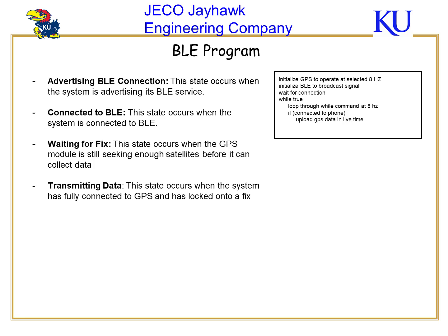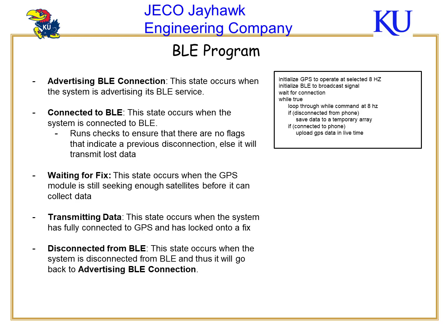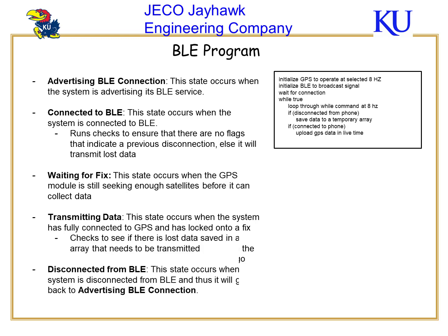This was a great proof of concept, but the only problem was that there was no way of reconnecting to the device or logging data when the device is disconnected from the phone. The second iteration of our program would ensure that upon disconnect, data from the GPS would be stored in a temporary array, and the BLE program would restart back to the advertising process to get reconnected to a phone. Lastly, our final iteration would ensure that the saved data within the temporary array would upload all the unsent data that was collected by the MCU, and then properly start feeding back real-time data.